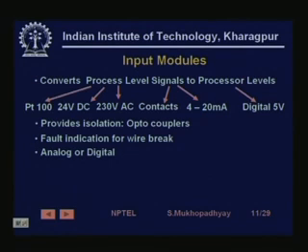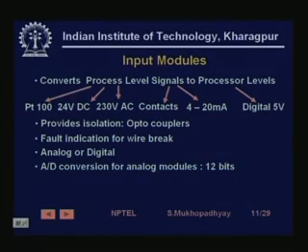They are generally of two types. They are either analog inputs or digital inputs. We understand the difference between them, right? So for example, a contact would be a digital input, and a platinum RTD would be an analog input. So obviously, for the analog input modules, we need to have analog to digital conversion, typically 12 bits accuracy, multi-channel sometimes.